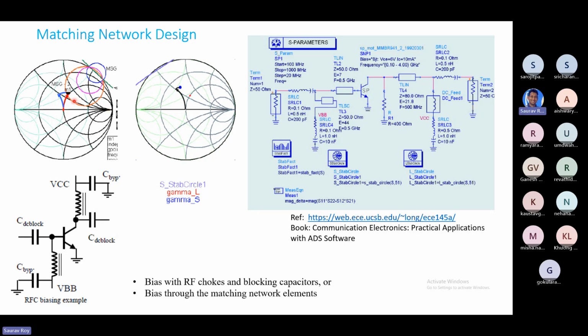And the corresponding impedance obviously can be found easily. Now our task is we have to design a matching network at the input side and at the output side. Why? Because ultimately our load is 50 ohm. At this point, this is the gamma L. At this point, we have decided the gamma L, and this side is 50 ohm.